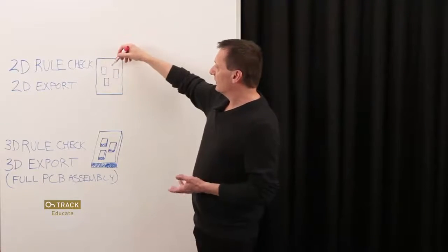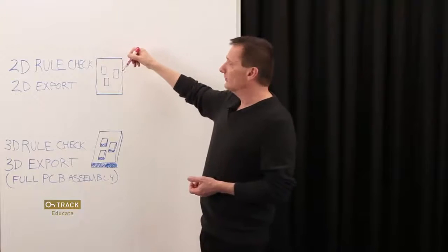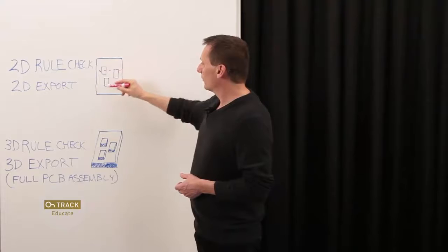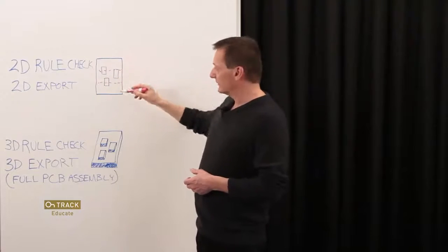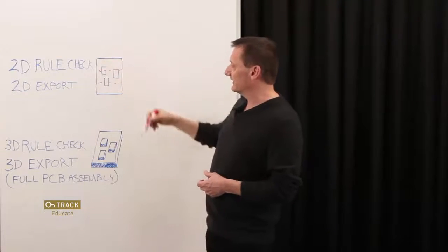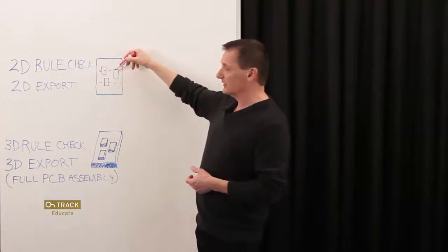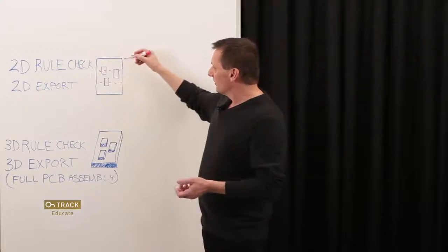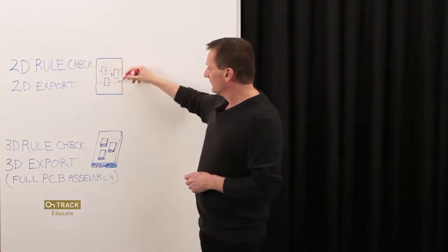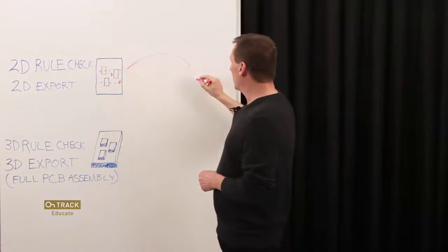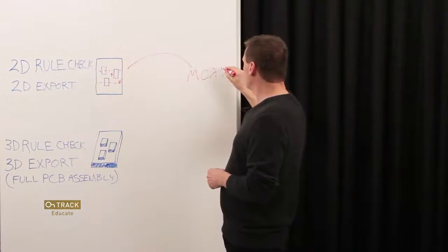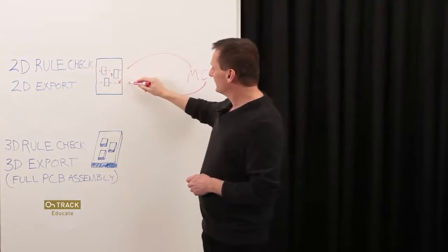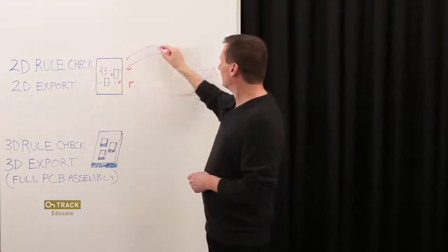The heights are not represented in a 2D model, so there are tricks and approximations that have been incorporated over the years where you can divide the board up into regions and then specify within a given region you can't exceed a certain height. But still, violations that occur would have to be detected by the mechanical team. And that path usually goes back sometimes several times.